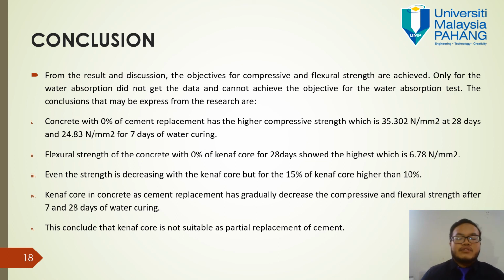The flexural strength of the concrete with 0% of Kenaf core for 28 days shows the highest, which is 6.78 Newton per millimeter squared. Even though the strength decreases with Kenaf core, the flexural strength at 15% of Kenaf core is higher than at 10%.